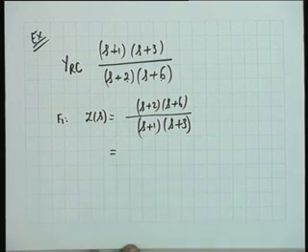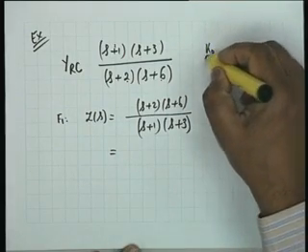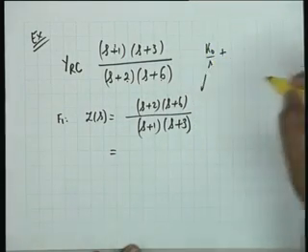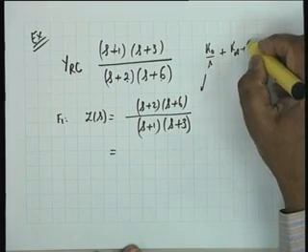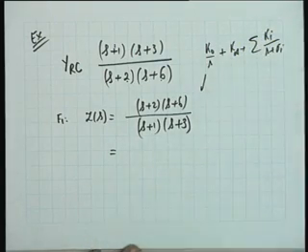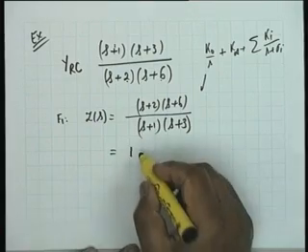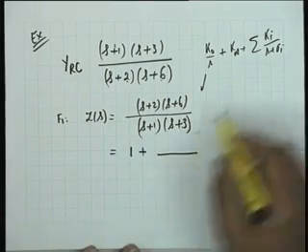Does the function have a pole at the origin? No, it does not have a pole at the origin. So, we have to take the infinite frequency value k infinity. The general form has to be k0 by s if it is impedance, plus k infinity, plus summation k_i by s plus sigma_i. What is k infinity? Oh, it's 1, since s squared over s squared is 1, plus terms of